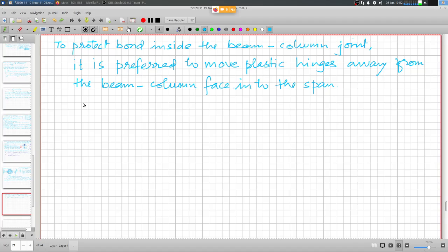and that shear force leads, obviously, to diagonal tension and diagonal compression, and it has to be taken care of by individual capacities, the concrete compression and the shear reinforcement transfer steel that has to go there, and obviously it is going to be in both beam as well as columns. So transverse reinforcement of columns as well as beams, they have to continue in the joint.